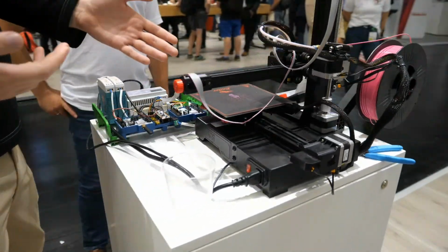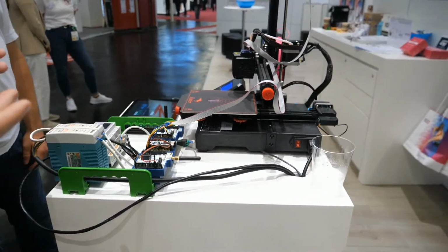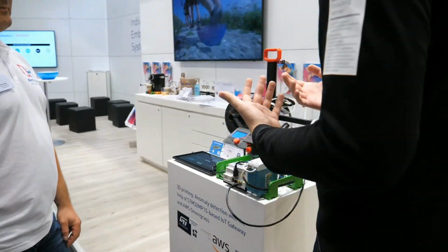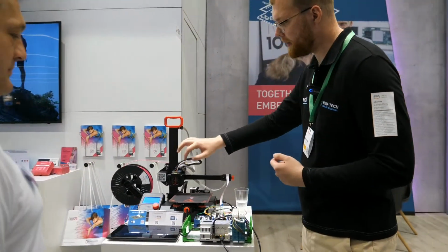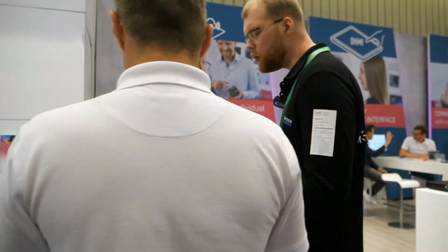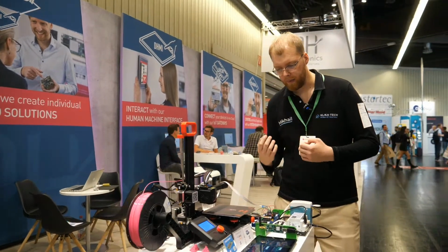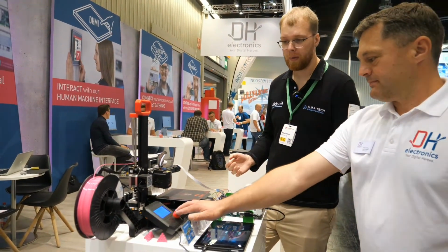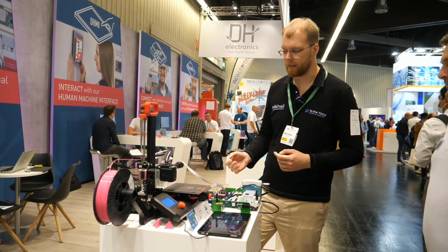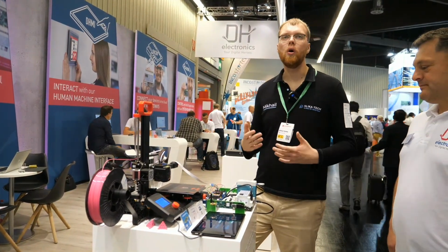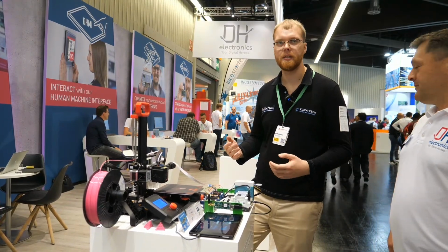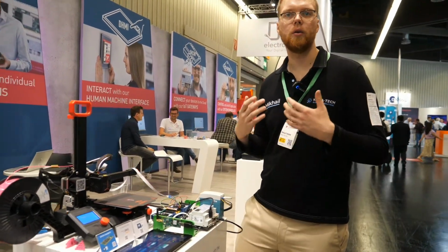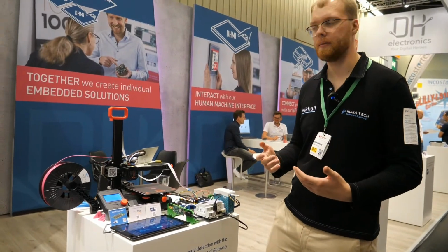So here we have a sample of industrial equipment, like a 3D printer, and we add additional sensors to this printer. Basically, it's a three-axis accelerometer, one here and a second here, and using data from these accelerometers, we send this data to our devices. There are two types of devices. One of them is the DH controller, and the second one is the microcontroller from ST. And we do machine learning on both of these devices in order to calculate an anomaly score, and that allows you to predict when your device should be maintained, when maintenance should happen.